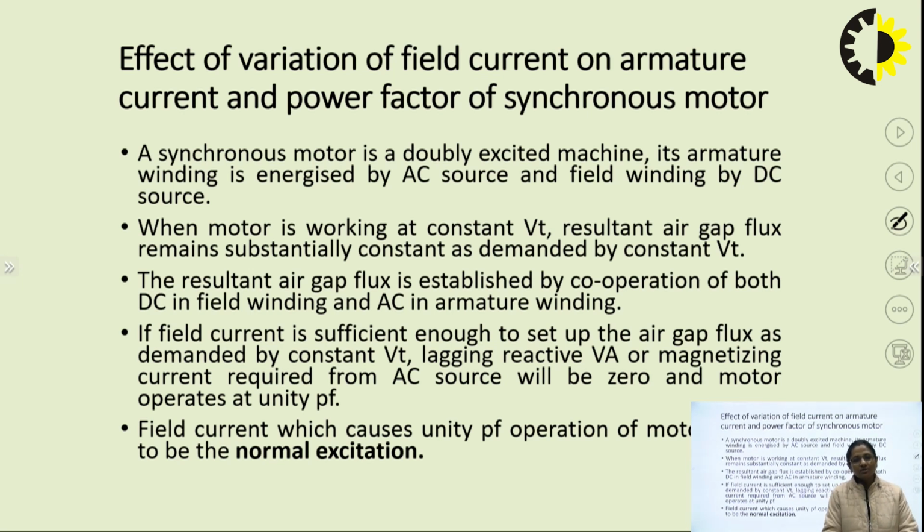We know that a synchronous motor is a doubly excited machine. We also know the basic construction and operation of the motor. We know that a three-phase supply is given to the three-phase armature winding provided over the stator of the motor, and a DC supply is given to the DC winding provided over the rotor of the machine, right? Now, if we vary the excitation, the DC supplied to the rotor winding of the machine, a particular behavior of the synchronous motor is observed.